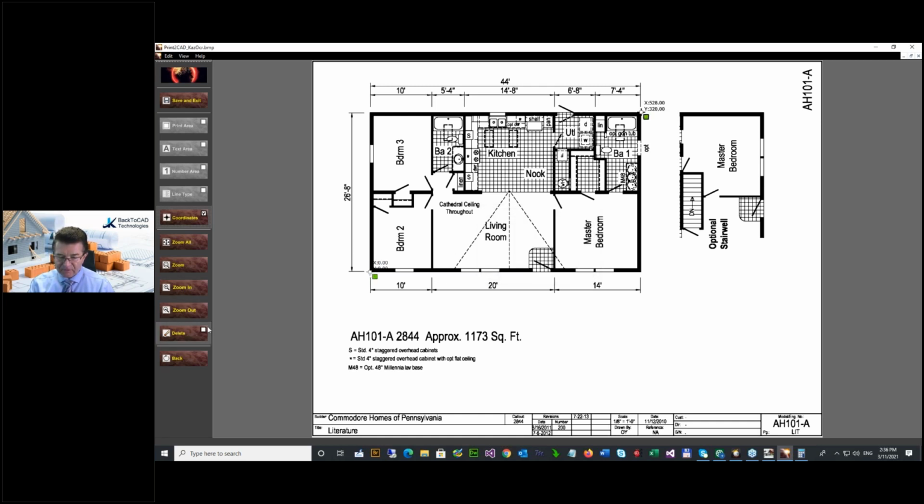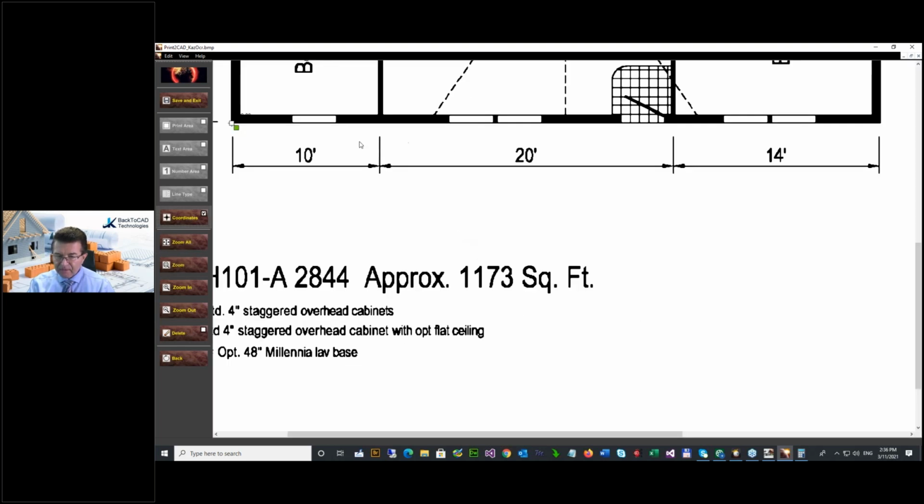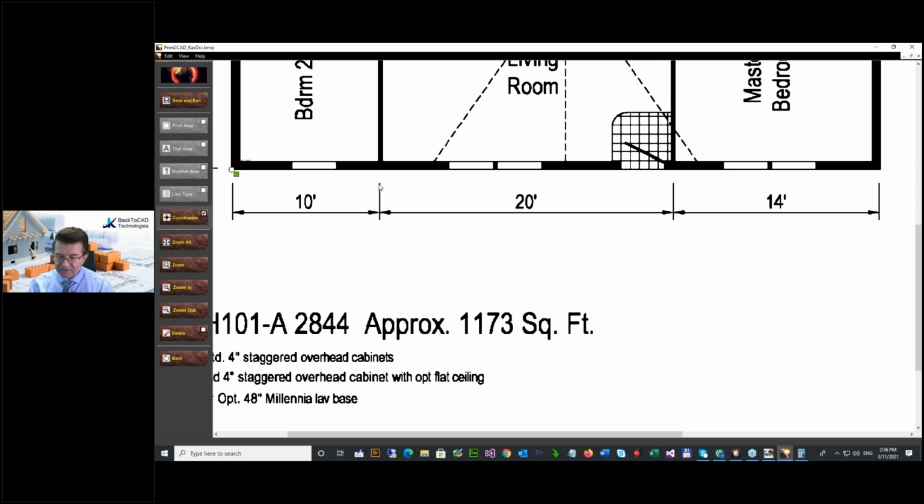But I will put another calibration point. Look, you can put the calibration point here. Here we have exact information. Let me put it here. And this time I calibrate only the X coordinate. The X coordinate is 10 feet, it's 120 inches.